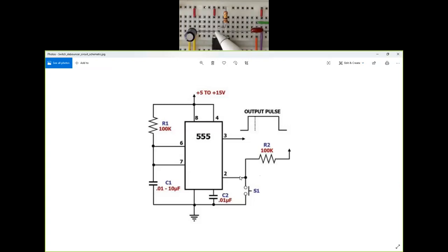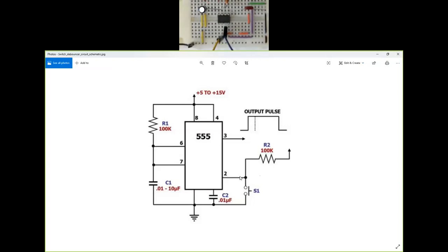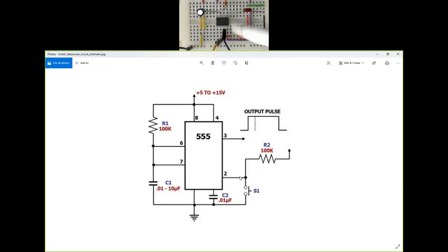And then from pin 7 to ground using those two yellow wires, I have a 1 microfarad capacitor there. So to zoom out a bit to show you how that is done. Pin 7 is the positive side of this 1 microfarad capacitor. The negative side of that capacitor is connected to that yellow wire to the ground terminal there.